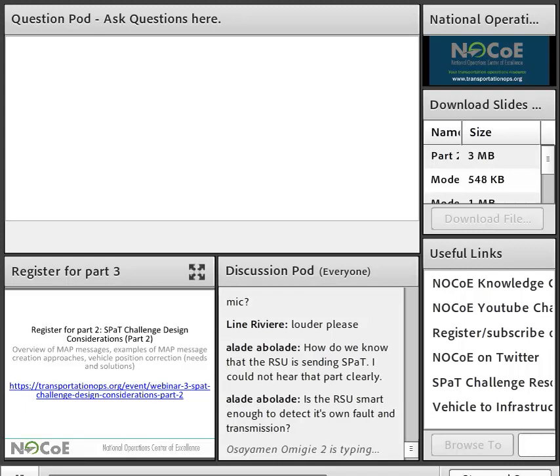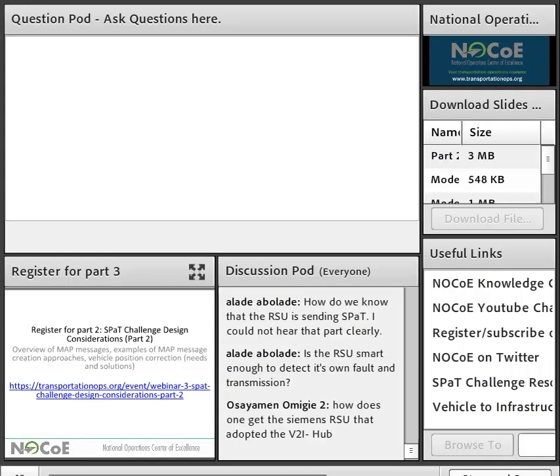Thanks. While I have you on, there's another question on V2I. Is V2I supported on Trafficware hardware? I'm not aware that they've adopted it. It's available for them to. I think there was also another question about which hardware or equipment is most used, at least in regard to the V2I Hub. It works with the Cobalt controller. We have it with the Econolite ASC3 and the firmware 2.58 or greater, and then we also have it with the McCain ATC rack mount. And then I know there's a Siemens controller that has adopted those NTCIP 1202 data objects, and then most RSUs that are compliant with the 4.1 standard of the message forward would be able to work with it.